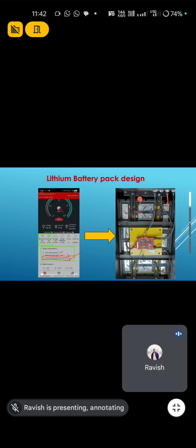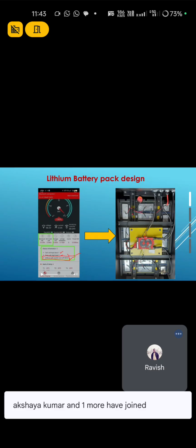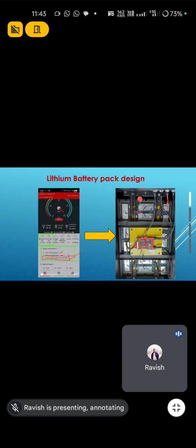And where is the BMS installed? And here there is the key, KEY. If your BMS switch is turned on but here it is showing turn off, you need to check the key terminal. You have to reconnect the key connector, then you can connect the battery with the application and show here. This will remove the error code, then your battery gives the output voltage properly.